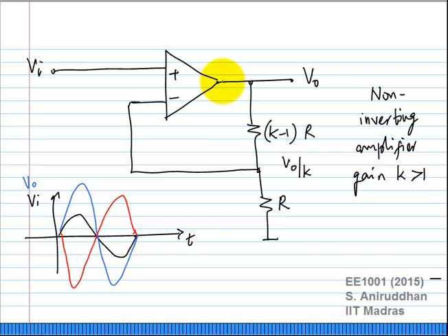Okay. Now let us say this error voltage is VE. In steady state, what is the value of VE? 0, right? If you have an ideal integrator here with any omega u, you apply a DC voltage VI, the output will go to K times VI, irrespective of what omega u is.